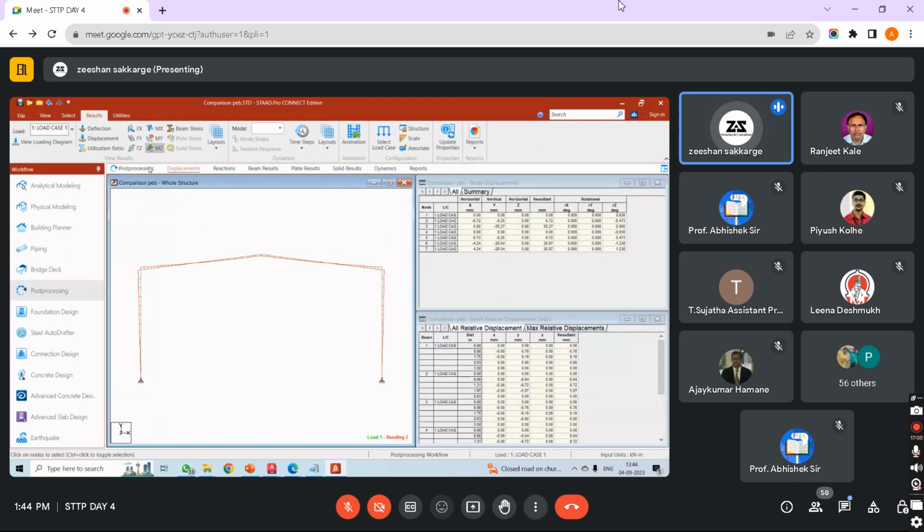Again, if you click on bending moment, you will have the same bending moment because this bending moment is a property of my loading and we haven't changed the loading. So bending moment will remain the same. We have the shear force that will also remain the same. We have this axial force. It will also be the same, but your members will change. The capacity of your members will change because from ISMB 250 now we have these tapered profiles.